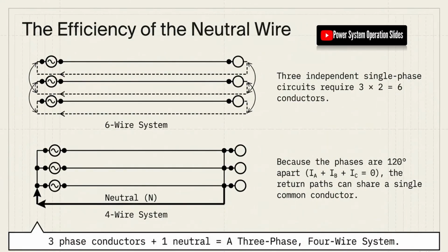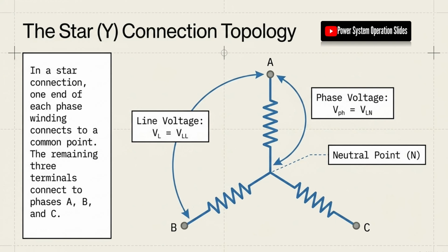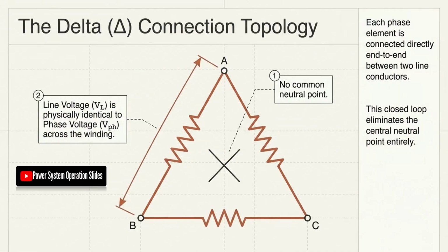An important technical advantage of the delta connection is its ability to provide a circulating path for triplen harmonic currents. Nonlinear electrical loads can generate third, ninth, 15th, and other triplen harmonic currents. In a star-connected system, these currents can accumulate in the neutral conductor. In a delta winding, the closed triangular path allows these harmonic currents to circulate within the winding rather than being transferred directly into the external network. This characteristic can help reduce harmonic propagation and improve power quality in the connected system.